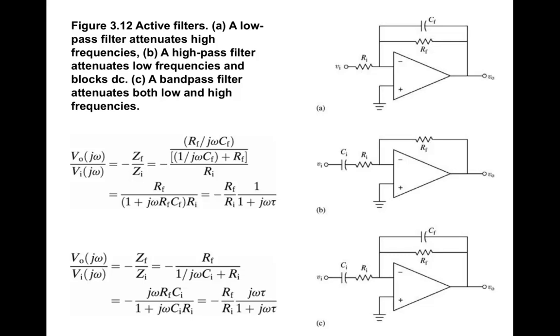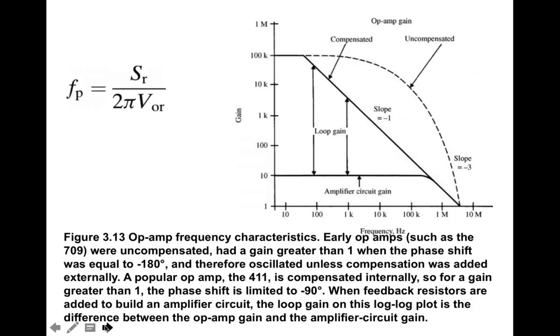This is just a little easier to troubleshoot, but it would use 2 op amps as compared to 1. Also, if you use 2 op amps in series, so you connect the output of your low pass to the input of your high pass, the advantage there is your transfer functions multiply. So that makes the math sometimes a little easier.